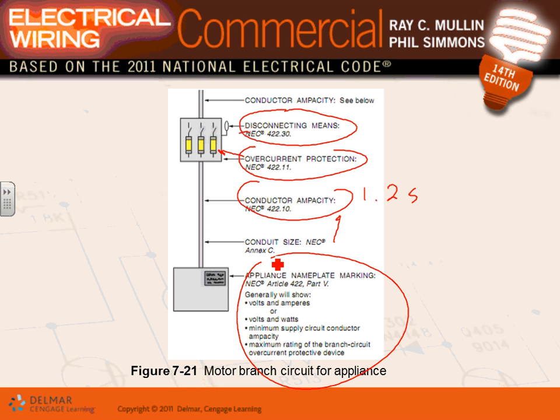Any comments, guys? Any questions? So for the most part, Adam, how do you size? You size your overcurrent protection device at 1.25. How do you size your conductors? 1.25. Conduit, of course, based on the conductors. Your disconnect for most of the time is 1.15. All these are the sizes you size it for this piece of equipment.